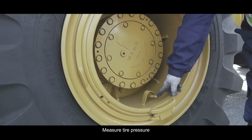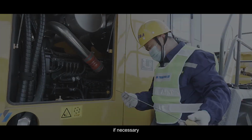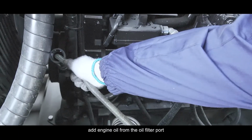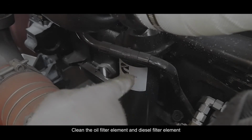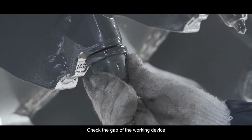Measure tire pressure. Check the amount of engine oil. If necessary, add engine oil from the oil filler port. Clean the oil filter element and diesel filter element. Check the tension of the fan belt. Check the gap of the working device.